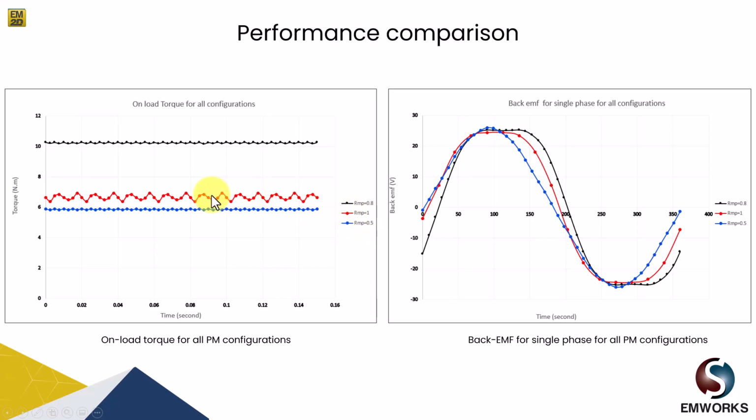Due to the usage of Halbach arrangement, we get two different torque magnitudes. One is higher compared to the surface mounted, and the second one is lower. That all depends on what ratio you have been using. So it's very important to optimize the ratio of your Halbach array arrangement such that it leads to a higher torque density of the motor.